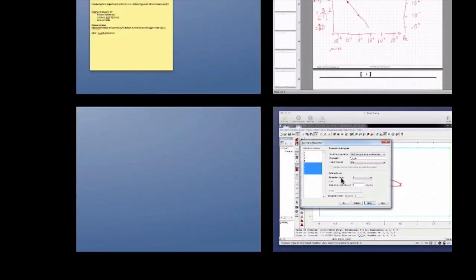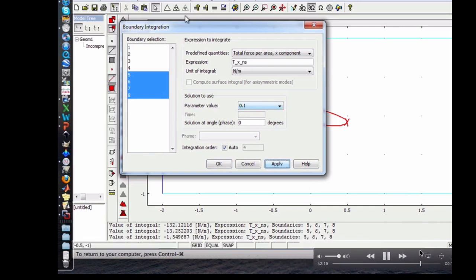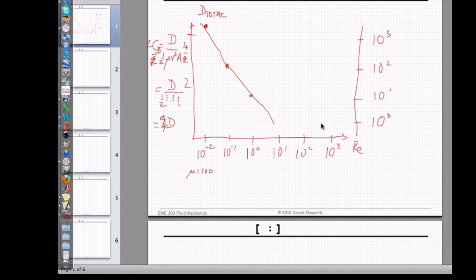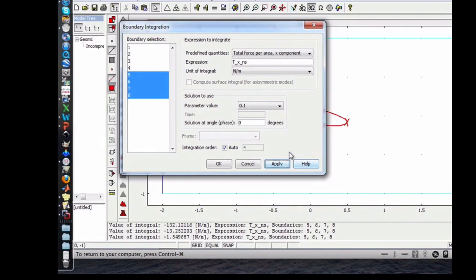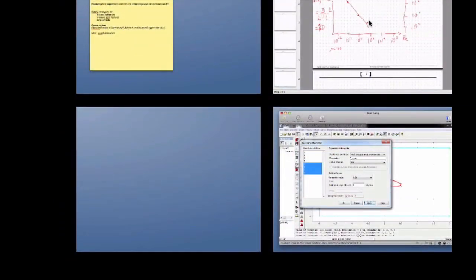If we do it for the next one, what's going to happen? This is a Reynolds number of 10, and it's 1.5. So it's not quite reduced. It should be 1.3, right, if it's going down by an order of magnitude each time. So it's not quite doing that. Now it's here, and this is 1, so it's actually a bit higher. It's almost linear, I guess you could make a case. If you come down another order of magnitude, then we end up with this, which is 0.1. Instead of being 0.13, now it's 0.3, so it's double what it should be otherwise. And so you get the picture, this is basically flattening out.